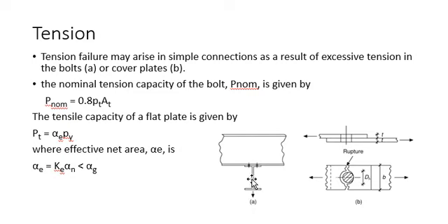So the pulling force would be translated to the tensile force in the connection. The more they pull, the more the tensile force. So the efficiency of the connection will depend on the connected part to resist the tensile load. Here we are looking at the bolts. So the bolts should be able to resist the tensile load that is being applied to them.